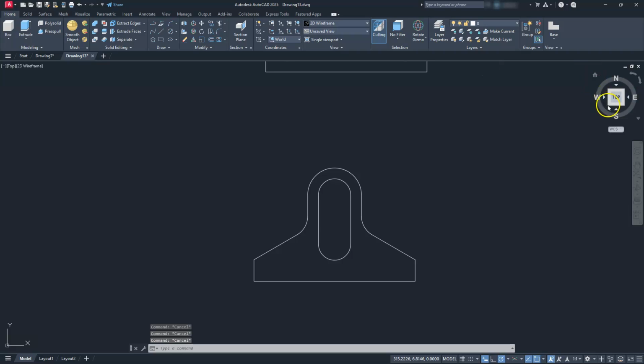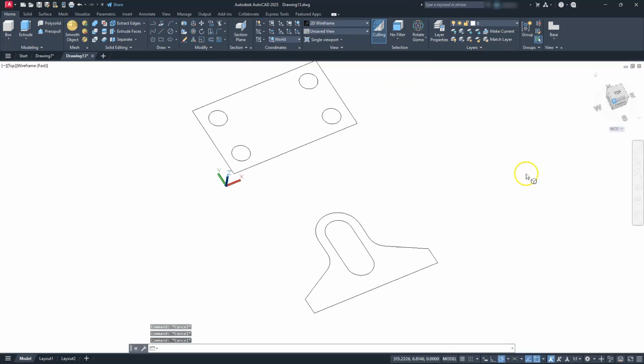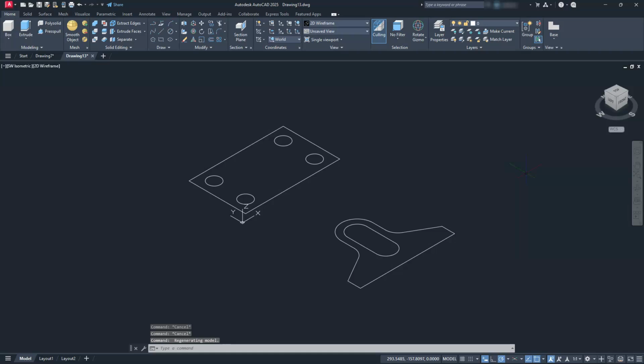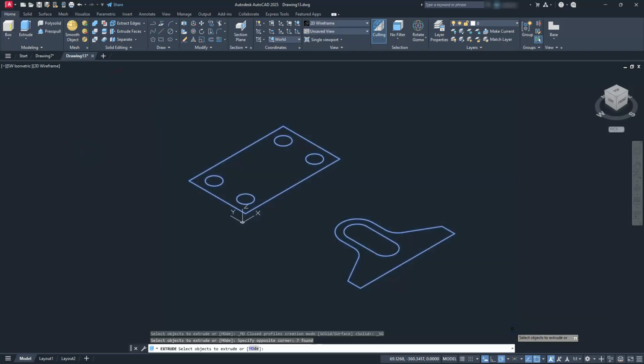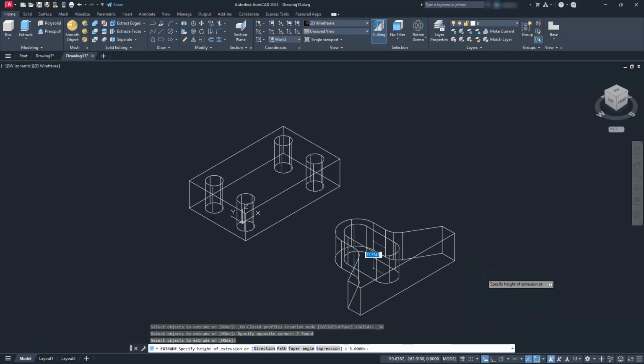Okay, now we have everything that we need to construct our 3-dimensional piece here. I just need to make sure that I realize which end is what. So closest to my UCS here is where the 20 starts, and it goes up that direction. Let's go ahead and do our extrusions, and both of these extrusions are going to be set to 10. So we'll go to extrude. We're going to select all of this. Go ahead and hit enter. And we can go either up or down a distance of 10.